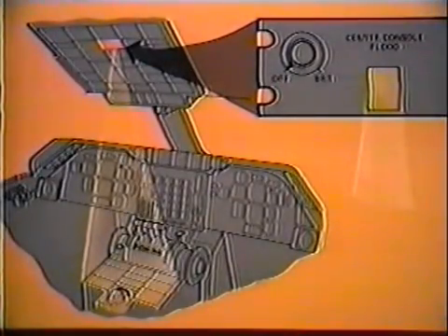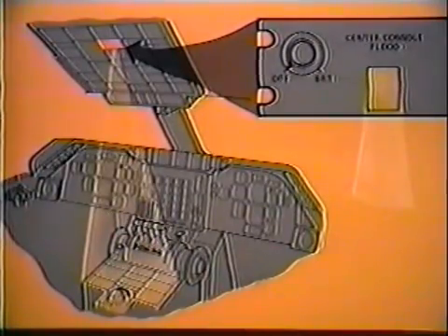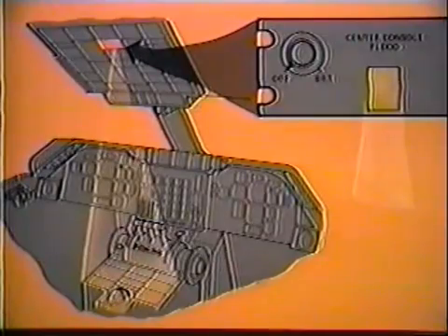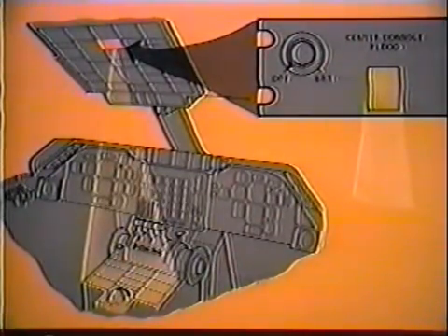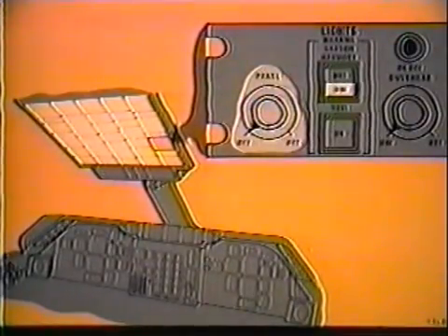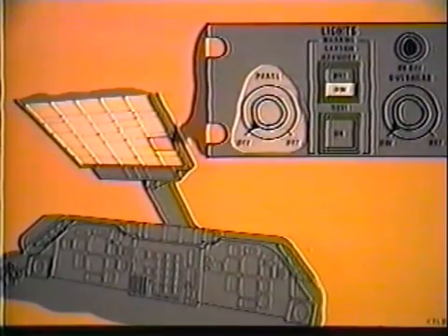There are 3 normal lighting control panels on the pilot's overhead panel. The first one to be discussed will be the center console flood. The center console flood panel contains a recessed floodlight and control rheostat, which floods the center console as shown. The second normal lighting panel is the lights panel. The lights panel contains the control rheostat for the overhead panel backlighting.